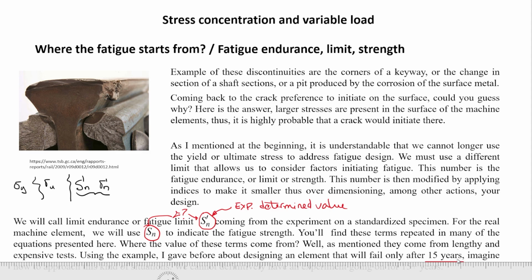So there are mechanisms that you can use to speed up the failure, and then you can scale up that reduced time failure and say, well, yes, it's more or less 30 years. In a nutshell, you can do that by either increasing the loads on your parts or reducing certain sizes or scales in your design, but everything has to be done according to certain similarity laws. Then you can scale back to the original part and see, well, yes, it's about 15 years. But no way you're going to perform an experiment during 15 or 30 years to see if in reality your design was correct or not. That's not done.